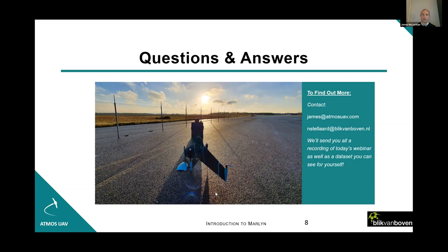Because we have a set of propellers that are specialized for the helicopter mode and a set of propellers that are specialized for the airplane mode, we're able to operate at our most efficient operating point for each of those flight regimes, because each of them has a specific RPM and torque that is required to be optimal at that point. I think there are certain drones out there that don't have that, which may limit your ability to operate at flight heights above about 3,000 meters. But with us, it's not an issue.